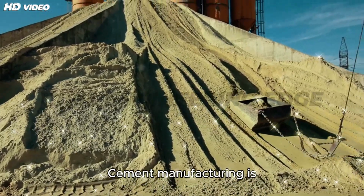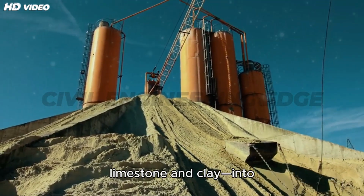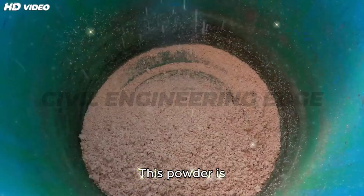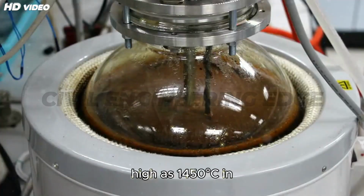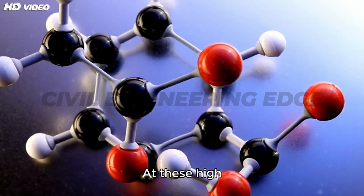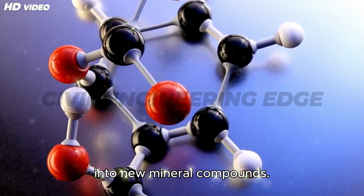Cement manufacturing is a complex process that begins with mining and then grinding raw materials, primarily limestone and clay, into a fine powder called raw meal. This powder is then heated to a sintering temperature as high as 1,450 degrees Celsius in a rotating kiln. At these high temperatures, the original chemical bonds within the raw materials break down and recombine into new mineral compounds.